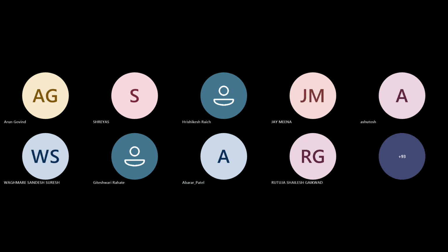Some might be 4.05, some might be 4.2. So if I take the maximum voltage within that string and the minimum voltage within that string, I will come to know what is the delta, what is the total difference within the cell. So that is the delta part. That is the voltage delta of the individual cell. And based on that delta, your balancing is being carried out.